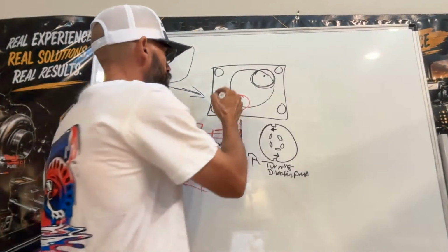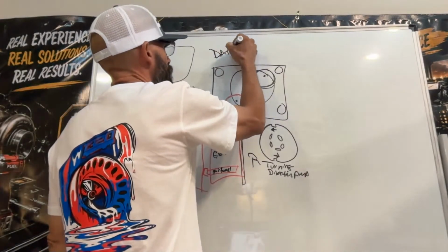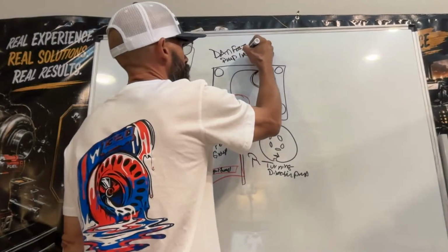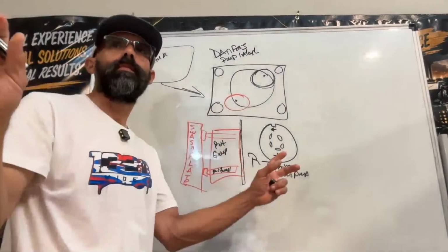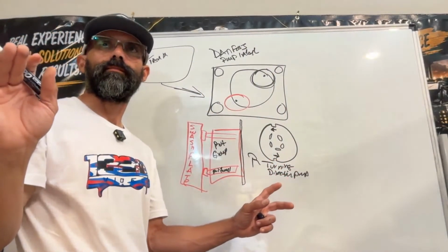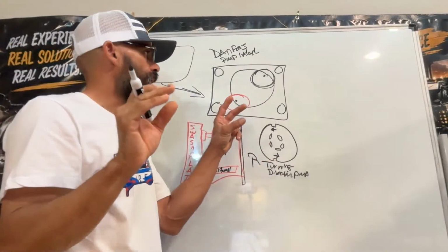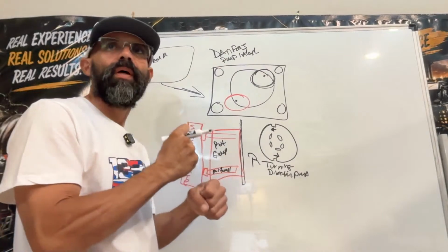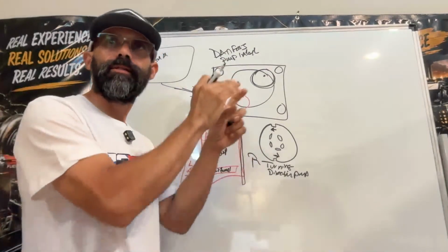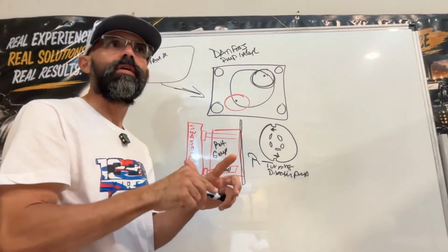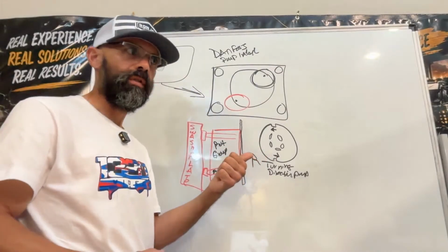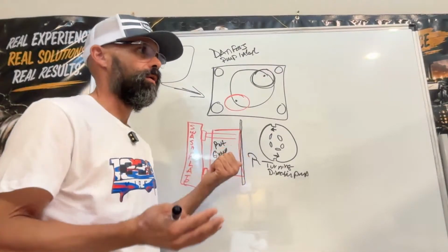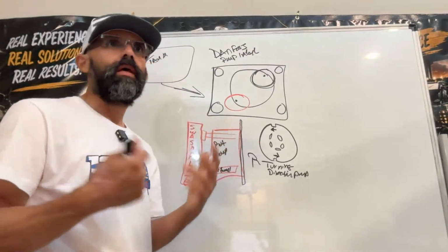Because it tells you, if you look on the pump label, you're gonna see a whole bunch of numbers and letters. That decal, it could be a decal, it could be a stamp plate on the housing, is gonna tell you, okay, it uses this shaft with a 14 teeth spline or, I don't know, a 20 teeth spline.